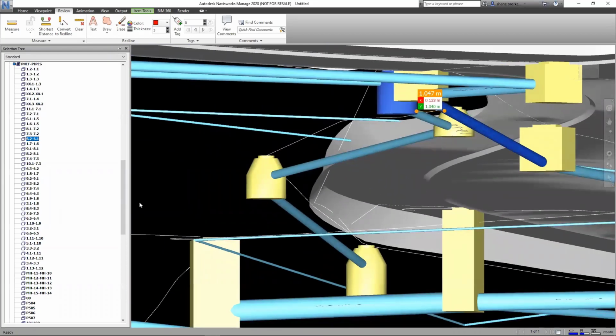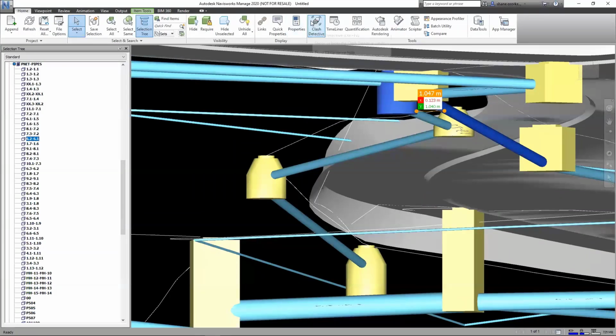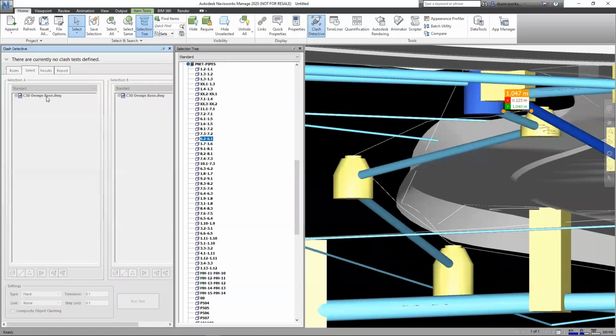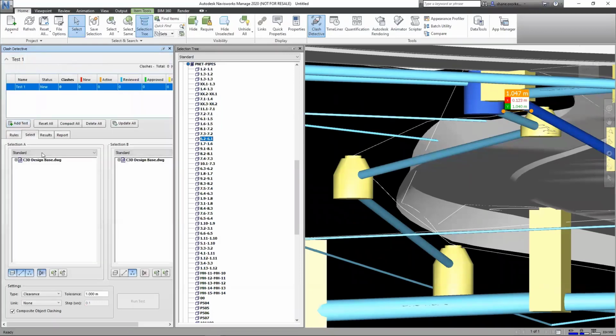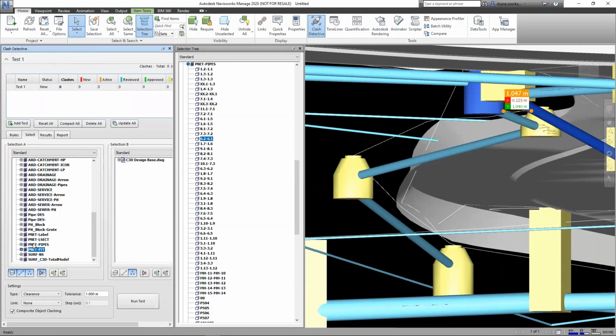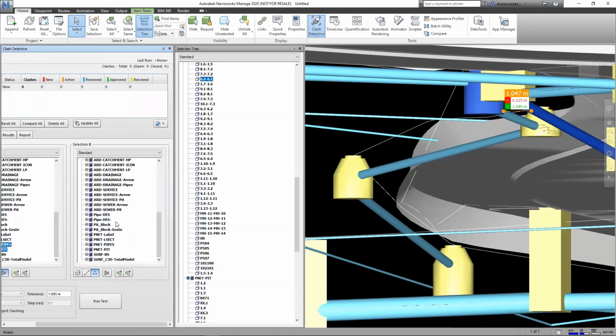If I want clash detection in Navisworks, then I should open up the Clash Detective. And then here you create a test, right? So I just need to add a new test. And what I'm going to do is compare the network of pipes and the network of pits. If I self-intersect them, I probably will get the lot, but I'll just compare it to other objects.